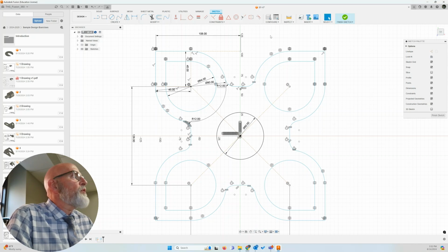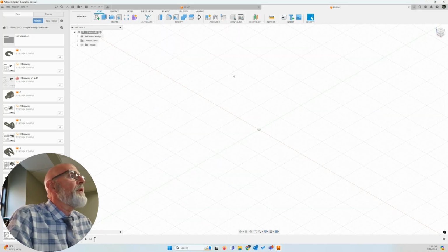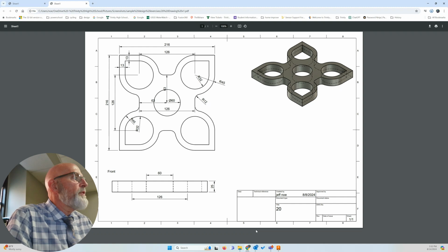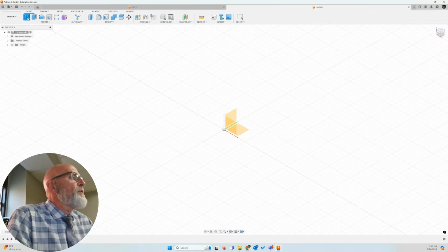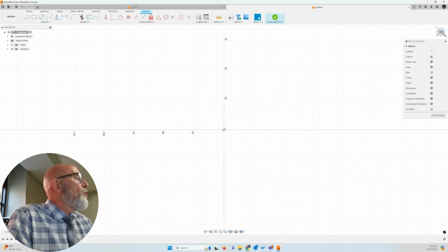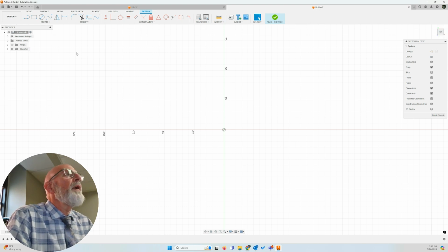I haven't done this project that often. There's my sketch from the previous attempt. First thing to look at, let's go back to our dimension sheet. What orientation are we going to start with? It looks like we're going to build from the bottom up. So we're going to start our sketch on the top bottom plane. Let's close this, create sketch. XY plane, there it is. Top bottom plane. I know I'm on the top bottom plane because my view cube up here is showing top.